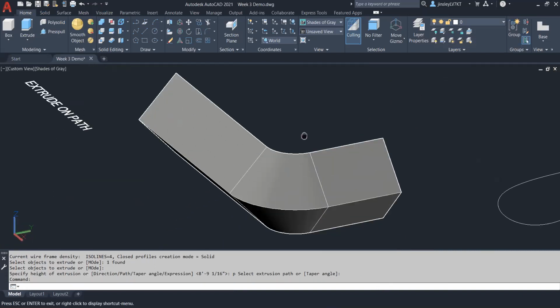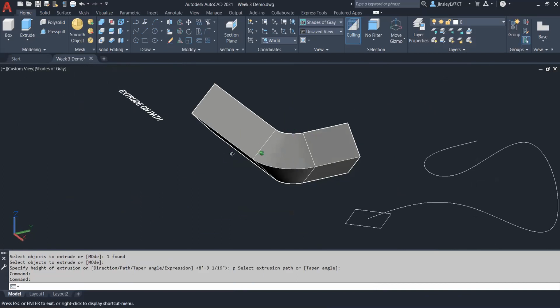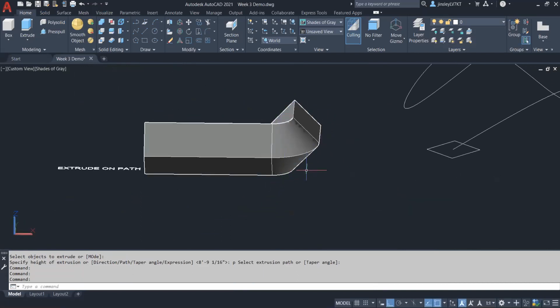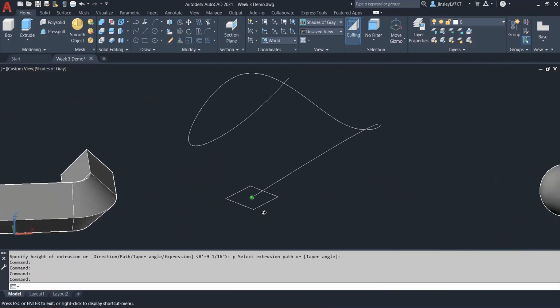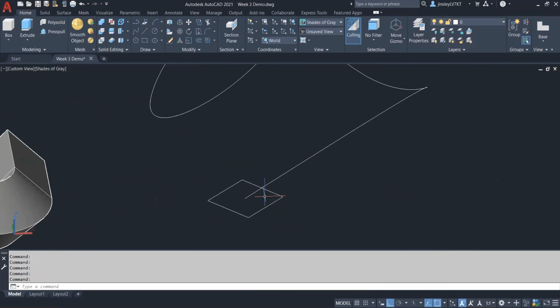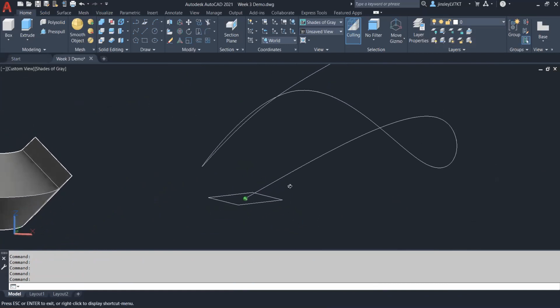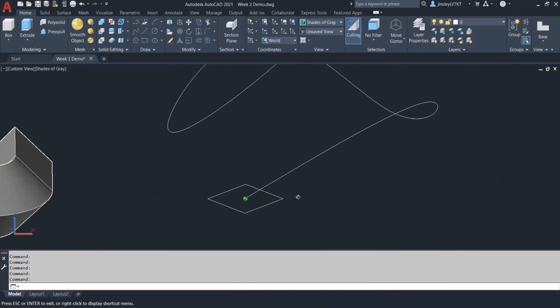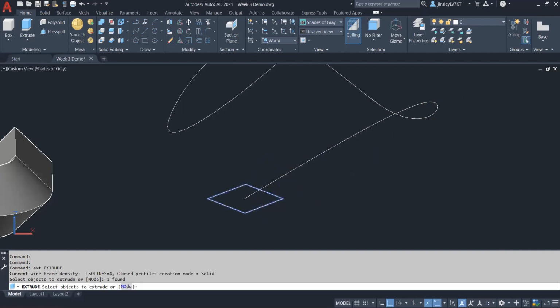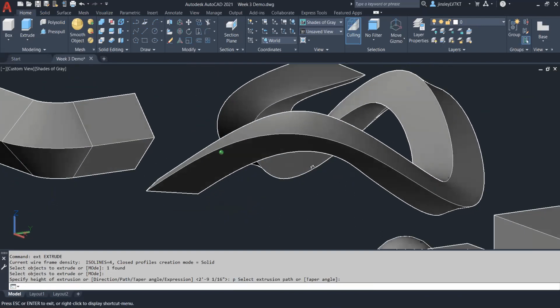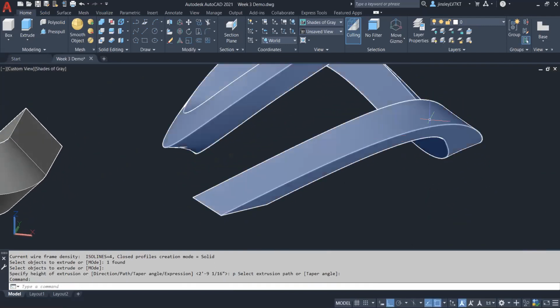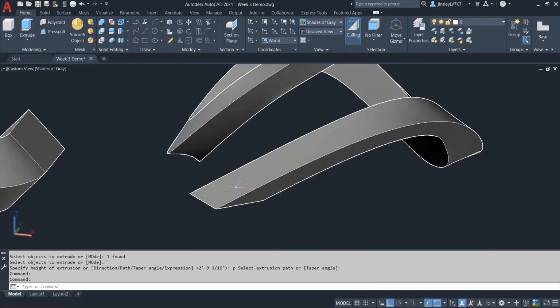So you have to be careful about how you orientate your objects and how you position them once they're in the proper orientation. In some cases, such as this shape here, orientating it is going to be tough, right? You would have to almost eyeball it, to be honest. So if I was to extrude it right now, actually I haven't checked to see if this will work. It should work. We can extrude it, but you can see that it's skewed. So we don't get quite what we want.